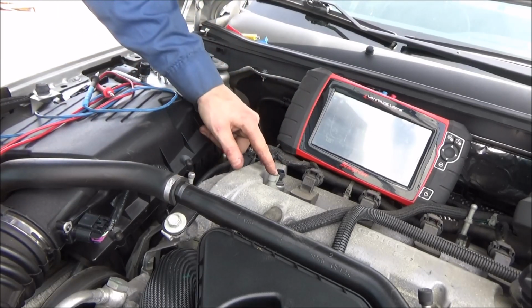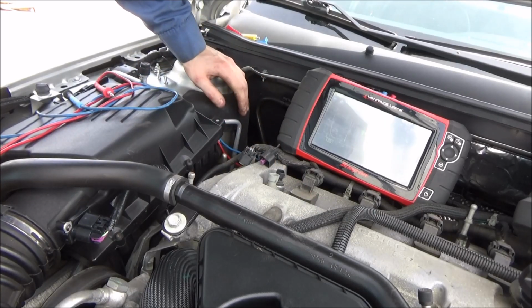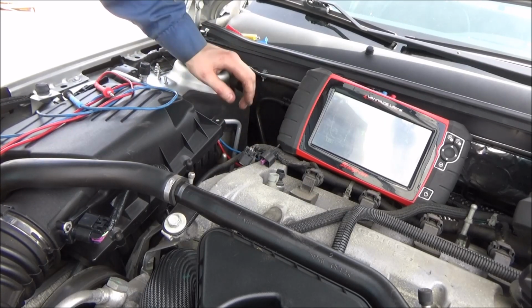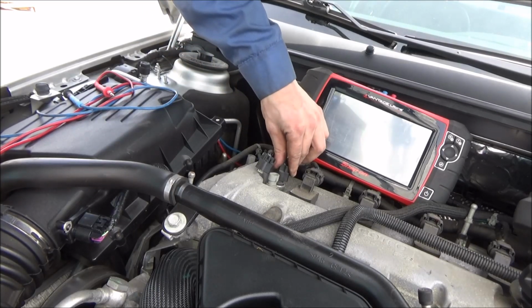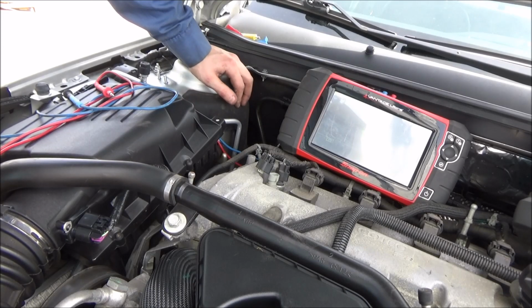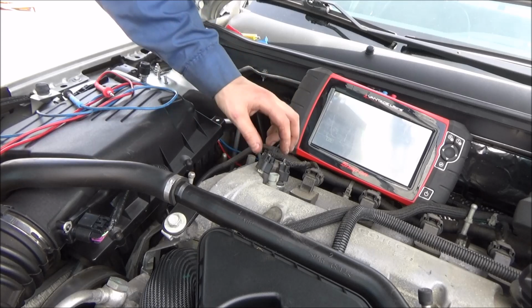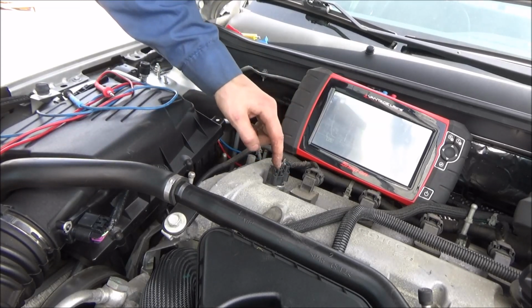But for this solenoid up here, we had a number about 100,000 ohms. That's way bad, guys. That's high resistance, no doubt. This rear solenoid back here, this exhaust solenoid, we had about 13 ohms, 10 to 13. That's generally what I see on these. So really the call for this car is going to be to replace both of these solenoids. And the type of failure we're looking at here is high resistance in this intake one.